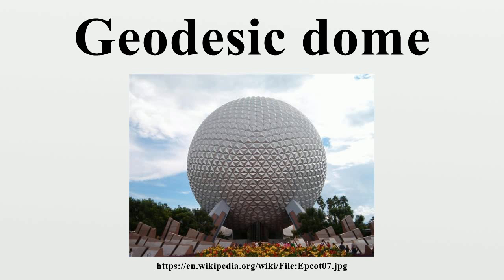Domes can also be constructed with a lightweight aluminium framework which can either be bolted or welded together or can be connected with a more flexible nodal point hub connection. These domes are usually clad with glass which is held in place with a PVC coping. The coping can be sealed with silicone to make it watertight. Some designs will also allow for double glazing or insulated panels to be fixed in the framework. This allows a fully habitable building to be formed.